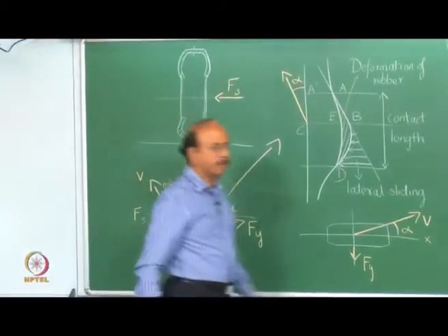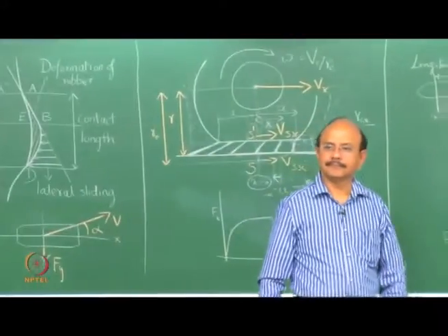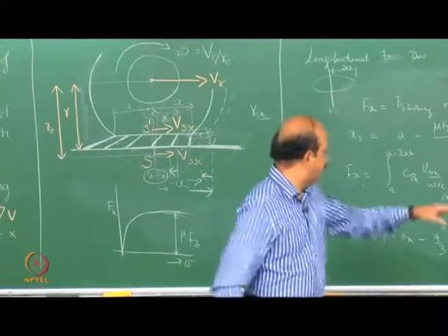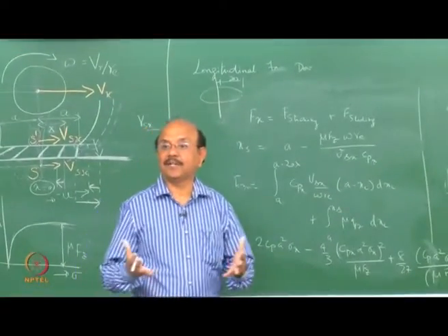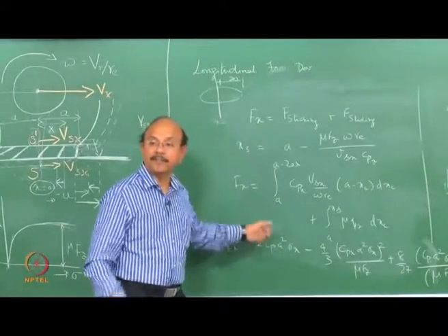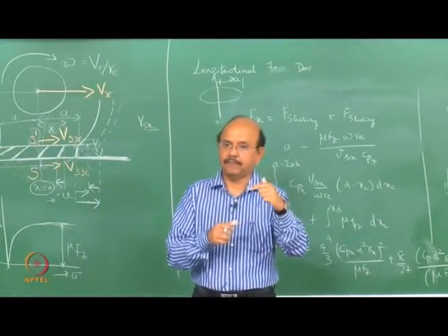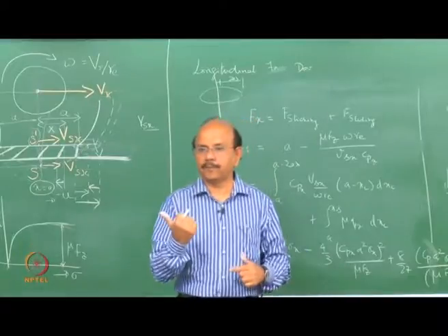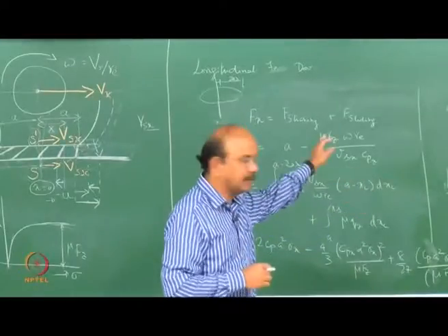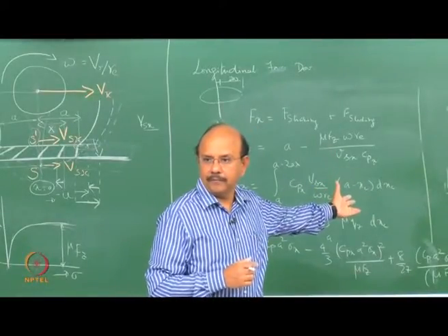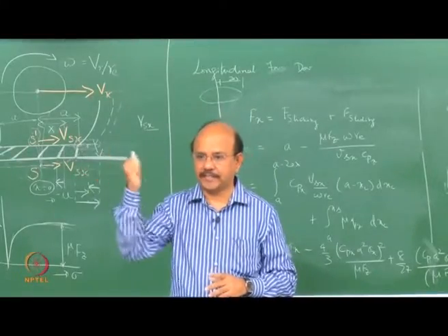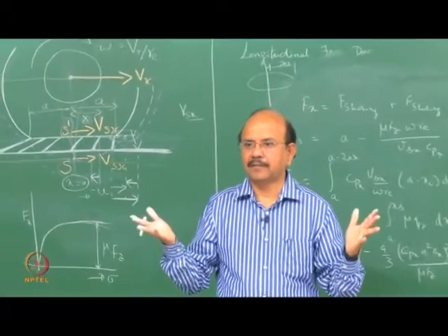Any questions here? When we equated Qz and Qx, that is possible when there is no slip, right? The condition under which the slip happens is where the Qx, the force developed per unit length, is equal to mu into Qz. This multiplied by dx, that into Qz is what I had written down there. So that's per unit length, so mu into Qz is equal to the Qx developed, when both of them are the same, then that would be slip.